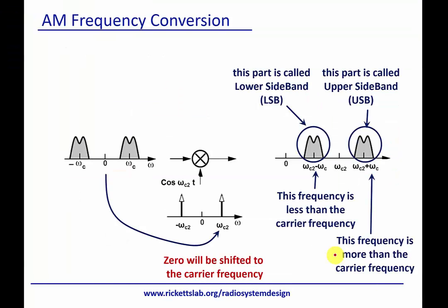All right, now that we've gone over convolution, we can go back to our amplitude modulation, if you will. And what we have here is just an example of, let's say our spectrum was a little bit more complicated, and if we multiply it by cosine, all we do is we just take this just like before, and the center at 0 is going to go right here, and it's actually going to go also right here on the negative.